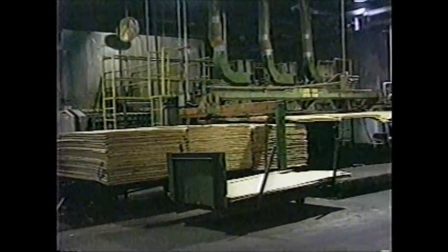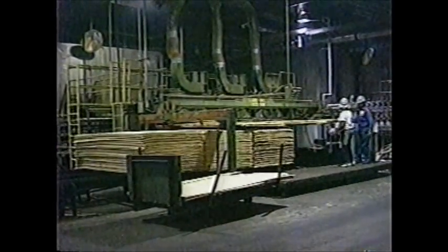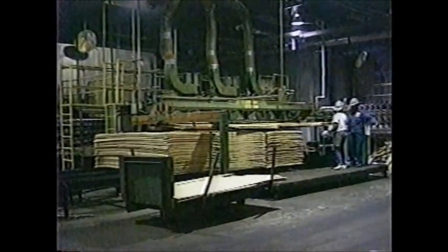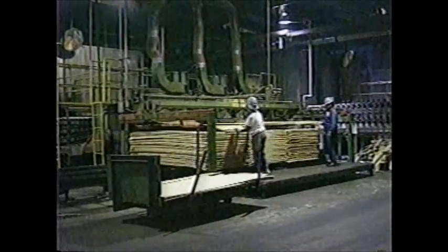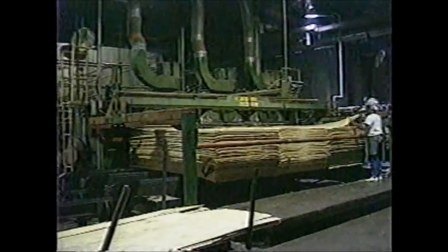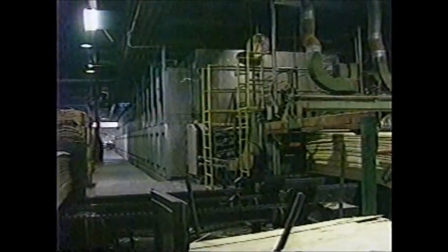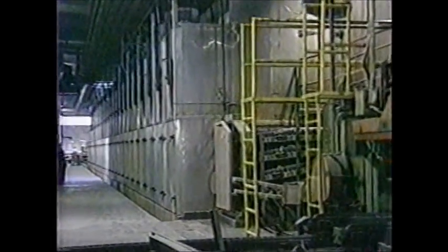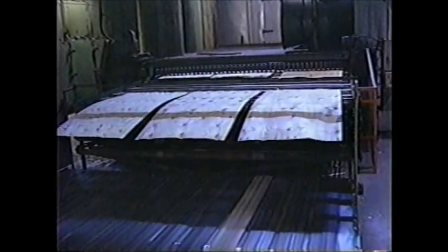After clipping, trimming, and sorting, the packages of green veneer are routed to the veneer dryer. The dryer maintains a hot, humid atmosphere in which the veneer gives up moisture. The veneer spends about 9 minutes in its journey through the dryer, beginning at a moisture content as high as 60 to 70%, emerging at a moisture content of about 5%.